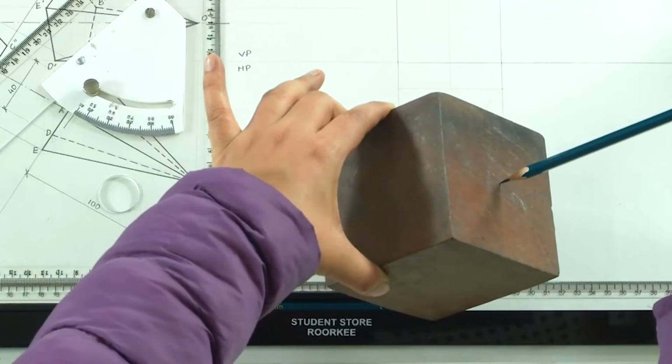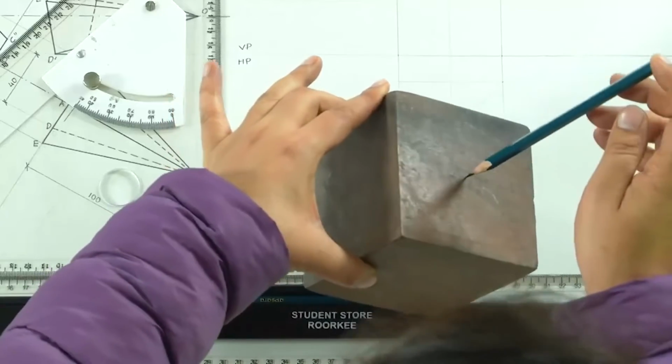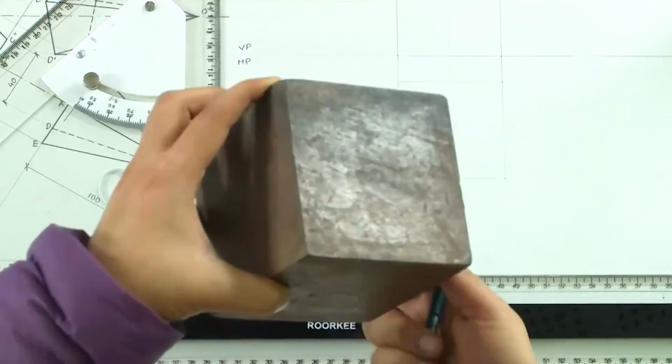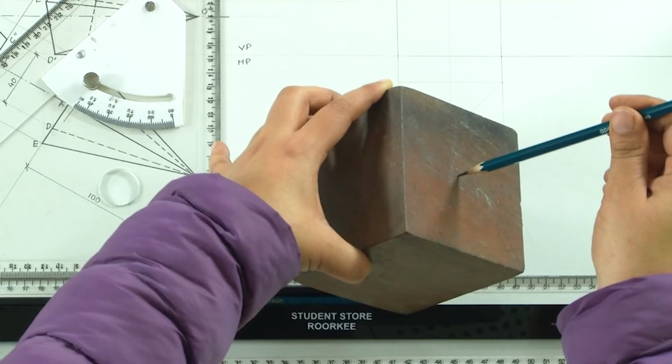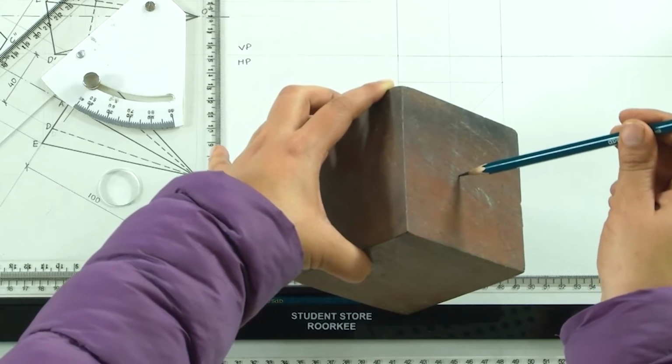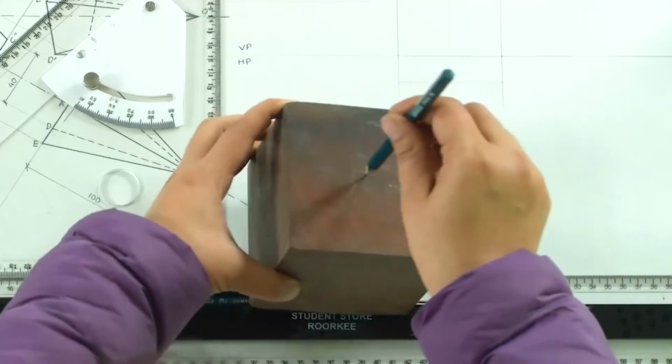So, in the simple position the cube is placed on HP like this and it has an axis perpendicular, and now we are saying that this axis is making an angle of 45 degrees with HP. So, if this was the VP, assuming it is parallel to the face of this and the square is kept in the simplest position, and now when it makes an angle of 45 degrees, the cube is resting on one of its edges and not faces, and it makes an angle of 45 degrees with the HP. So, the axis is still parallel to VP.